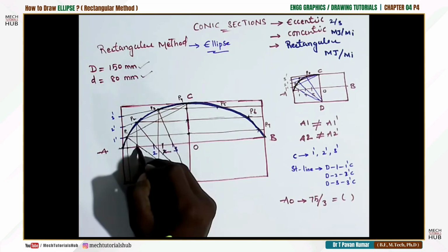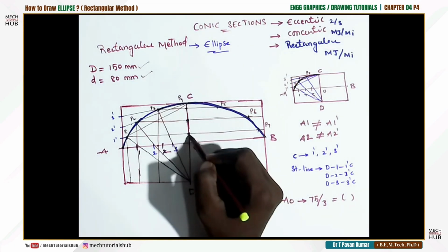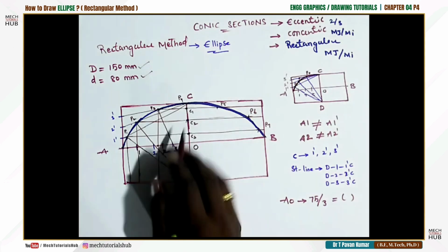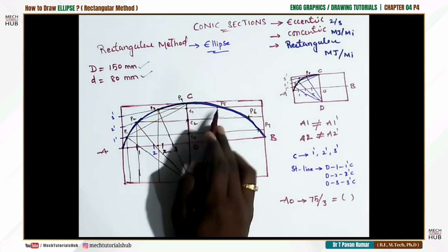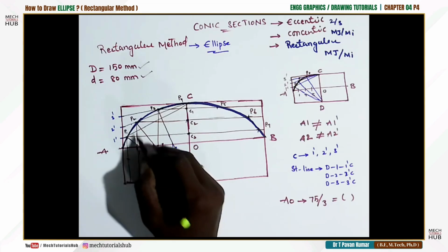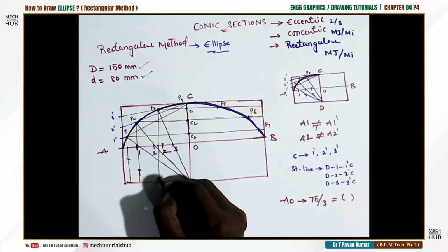this is one intersection, 2, 3. If you want, you can name these centers also. Let us name it as center 1, center 2, center 3. From center 1, you can measure this distance and make a mark. Similarly, measure this distance, make a mark. From here, measure this vertical distance up to P2, then make a mark. Similarly, from here, make a mark.